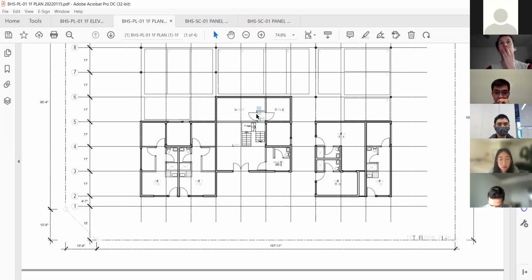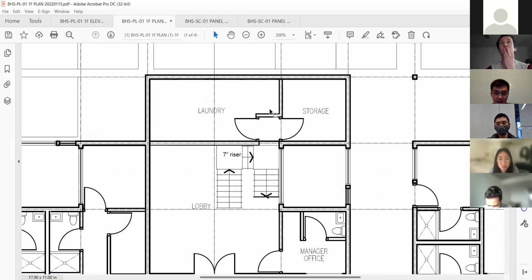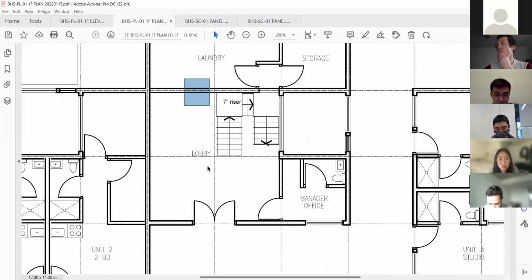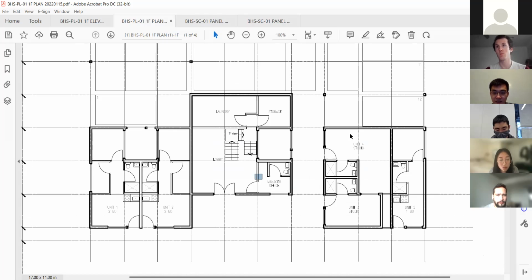Okay, and then just for information, the lighter lines inside here are the drywalls or the non-structural partition walls, and for these we just put 6 inches thickness. I'm not really sure about the common practice for the thickness of these walls.